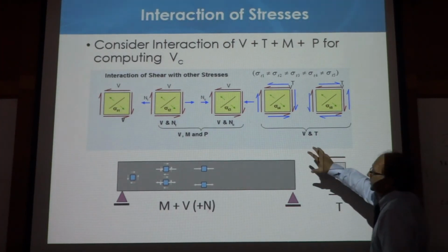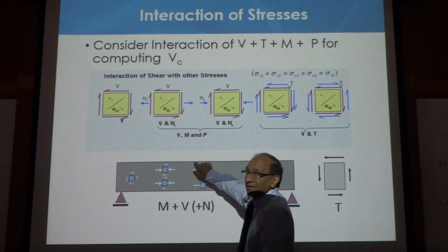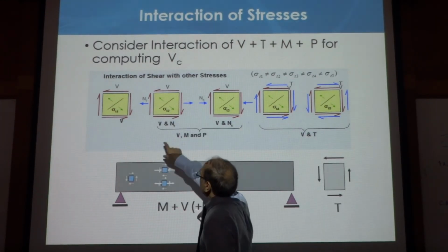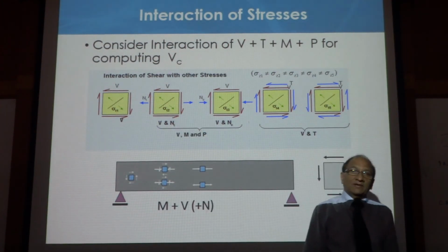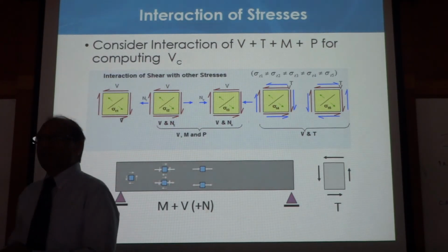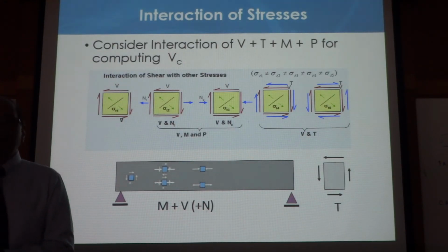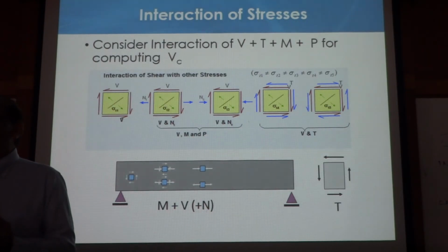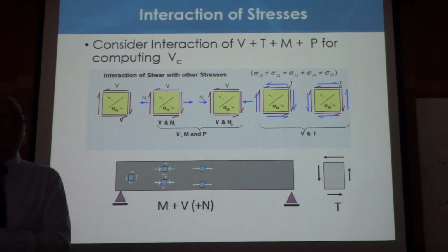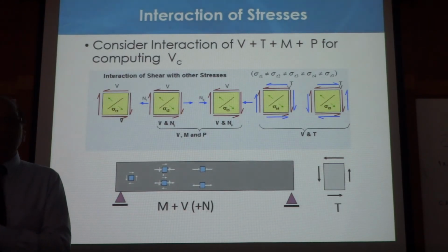And I also told you that on a beam we have many locations. Stresses change at every location, and this diagram keeps rotating in principal direction. So we have all these combinations, and I was telling you at that time that it's such a waste of time to calculate the concrete capacity in shear because it's too small and it changes all the time anyway. So now is the time to come and say, okay, let's throw that away. Let's not do that anymore. Let's not worry about the concrete shear capacity. Let's not worry about the concrete tension capacity and see what happens, right?